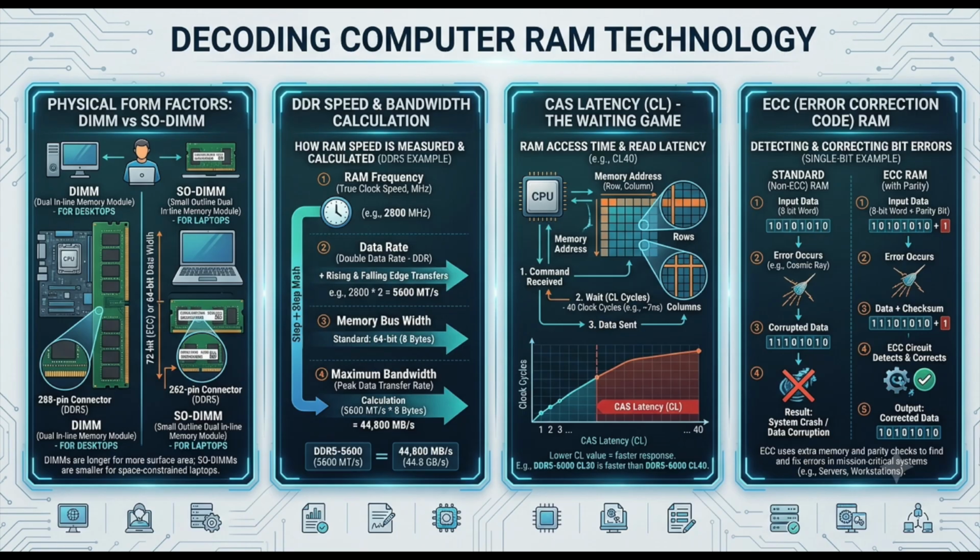Every component in the system, the CPU and the memory included, uses this common clock to keep track of their operations. So it's like a metronome for a massive orchestra. Yes. Perfect analogy. You have all these different components playing at blinding speeds, but because they can all hear the exact same tick-tock of the motherboard's clock, they stay perfectly aligned. And in the earliest iterations of synchronous memory, transfers happened at a single data rate. Meaning one transfer per tick. Exactly. On every tick of the metronome, the memory would transfer one 64-bit block of data. Tick, transfer, tock, transfer. But processors got way faster, and I'm guessing a single data rate just wasn't enough to feed them anymore. No, they were starving for data.